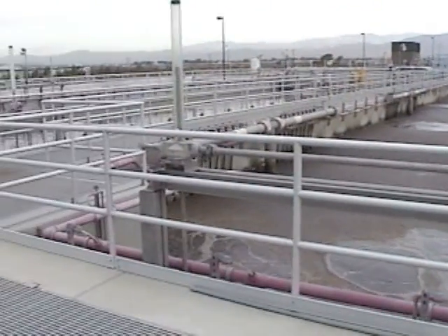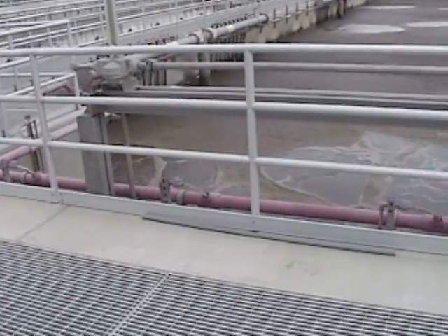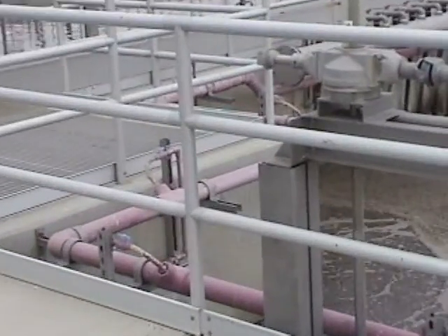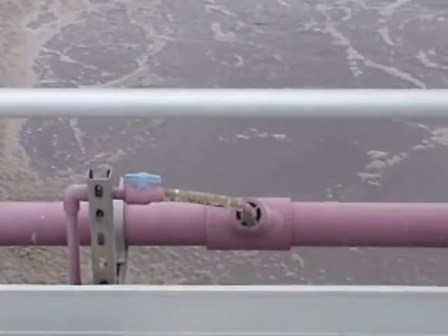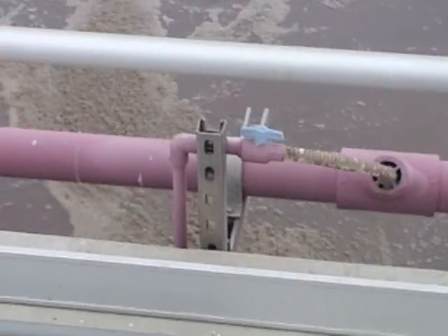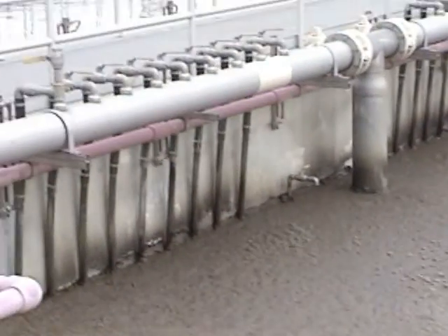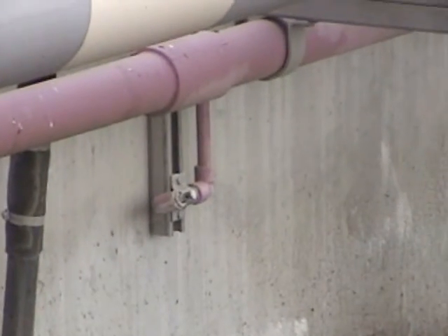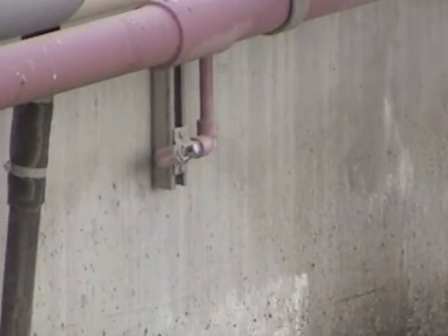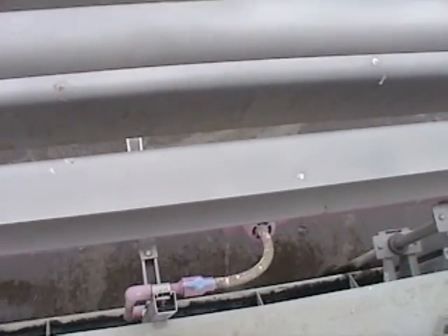The purple piping around the perimeter of the tank is utility water, and we use it for foam control. These are little spray nozzles all around the perimeter of the tank, and we use them to move foam out of the tank. Each one of the nozzles has a little valve on it so you can adjust the flow or turn them off or on. And then I'll show you down below where you can turn the entire system off or on.